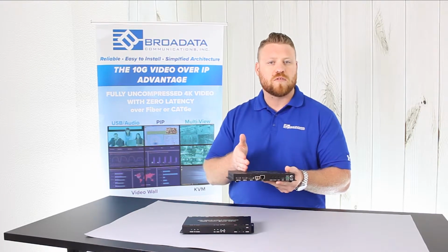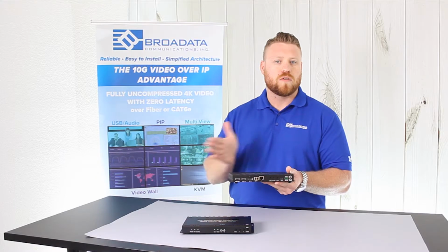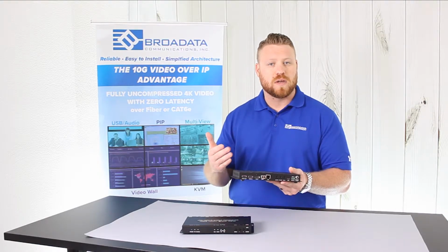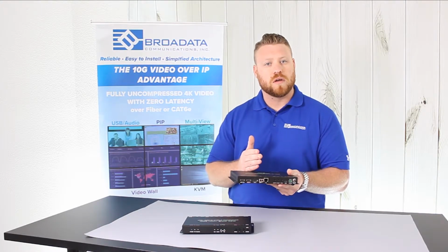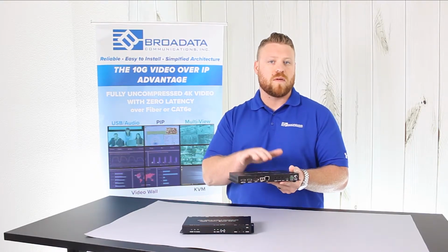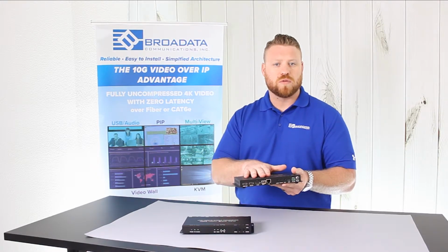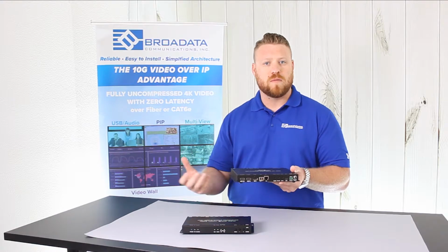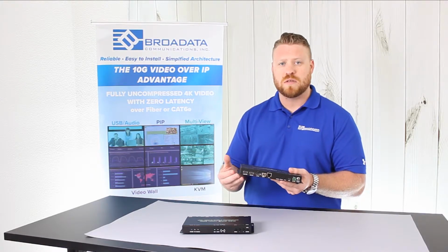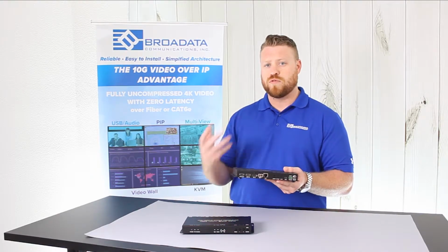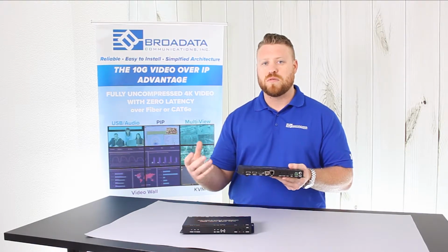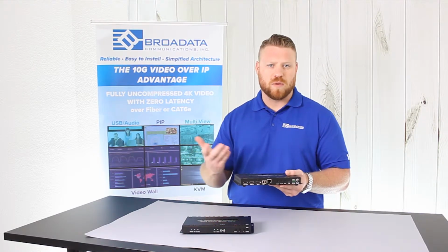So through the fiber transport, we can also transport up to 1 gig, a little bit higher than 1 gig of video network traffic. Now that's very exciting because not only does this transport uncompressed 4K 30 and 4K 60 signals for video, but it also provides you a very high speed network extension as well. So when you're using these in a pair, it helps to solve some network transport issues. I don't have to be running multiple cables around. Now in applications where you're using video over IP solutions, whether it's command control rooms, conference rooms, training rooms, I now can extend my network connectivity out into the projectors, out to the monitors, where I can use that for control rather than having to run separate cables.